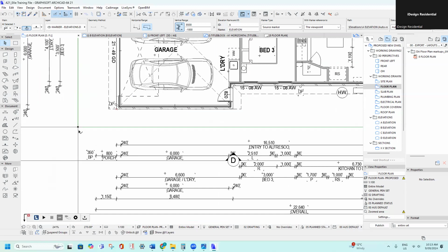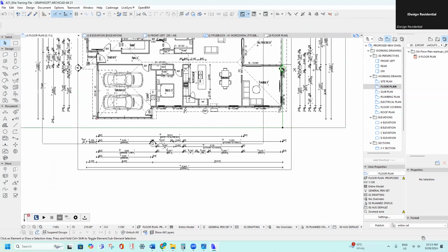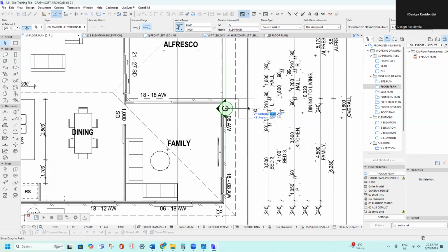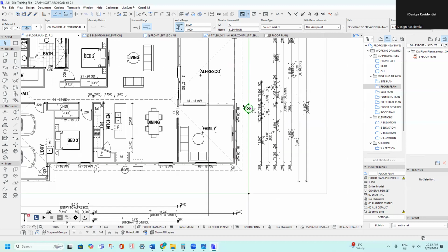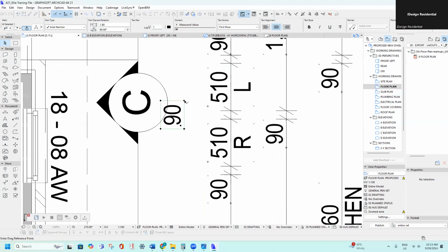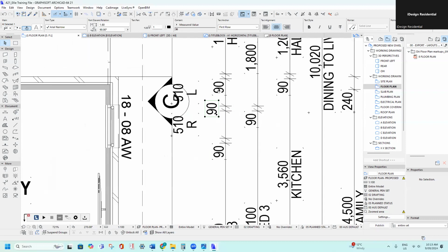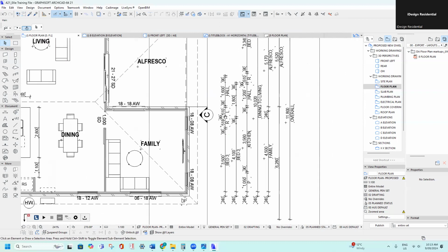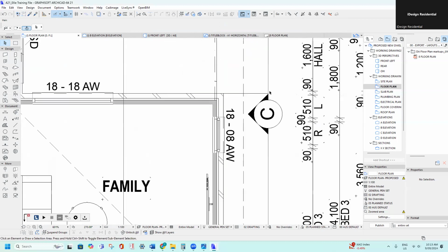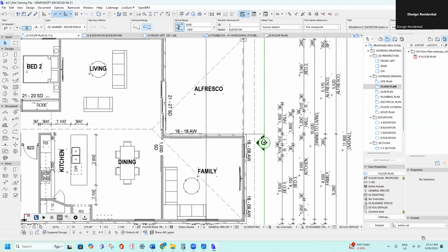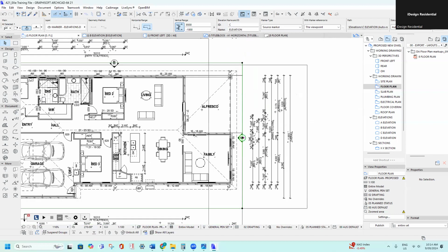if you click on that, you can see it finishes there. So that's why I just used that as a reference point. Just a quicker way to do it. And then drag it off a meter. And you can see the dimensions are a bit close. You can see there's still one dimension that's sitting up there. It needs to be dragged back down to there. And then again, you need to drag that back down and this one back down. And it's a bit close to that concrete there, like I previously said in a video. So I'll just bring it down a little.